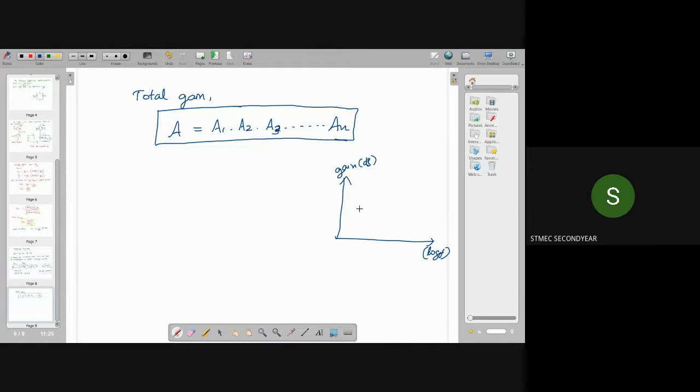Normally for a common source amplifier, we will obtain the frequency response like this, right? And here we have the maximum gain, and here we are taking a point 3 dB below, and these 2 points are called cutoff frequencies, that is lower cutoff frequency and upper cutoff frequency. Bandwidth is equal to fh minus fl. So this is the bandwidth of a single stage amplifier.